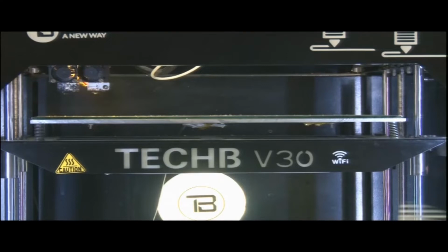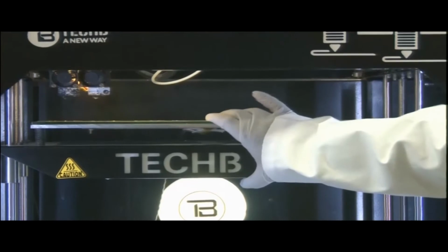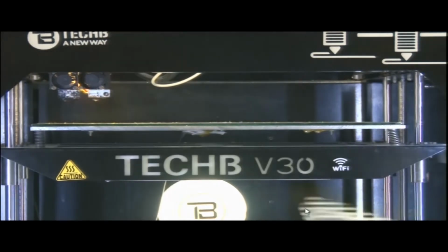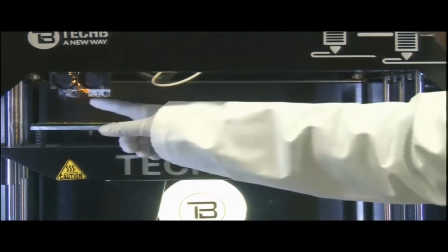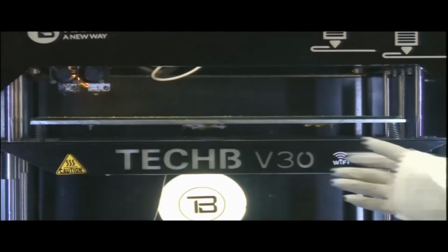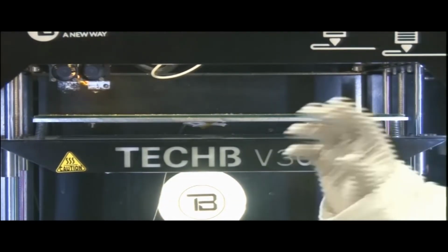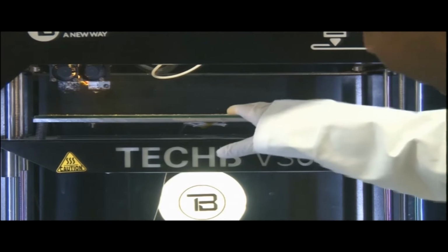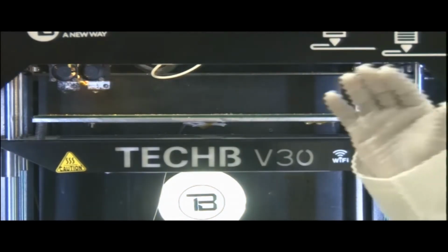When we fabricate a model of big size, the height increases, and sometimes it will vibrate due to the height, and the gap will vary. That is why the spring loaded mechanism helps to adjust the movement of the nozzle. You can see the spring mechanism here. In this way, we level the bed. Also, whenever we go for calibration, we use these screws to loosen and tighten and make sure that the bed is flat and secure with its adjacent surface as well.